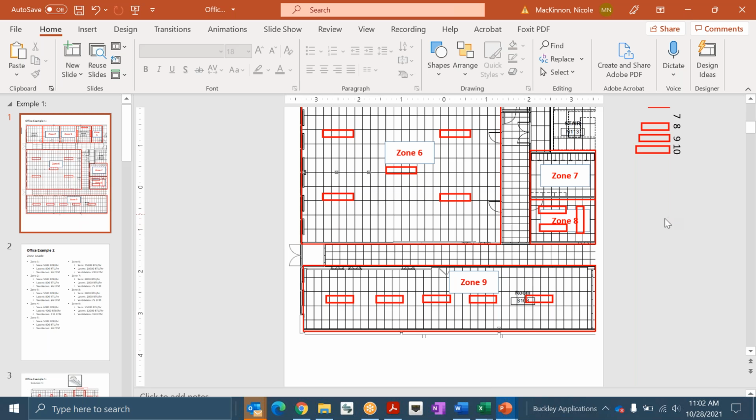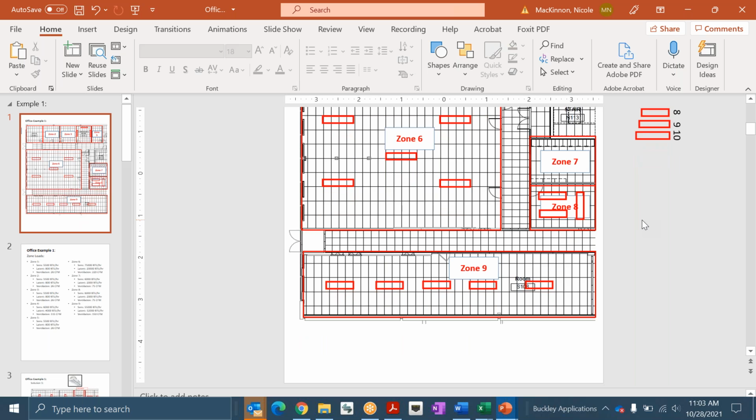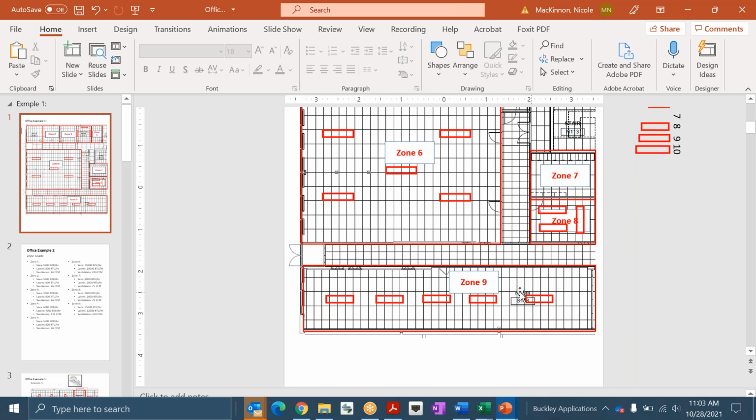Maybe you have a lot of glazing, a lot of solar gain. You don't have a high enough U value on your windows. That could cause some issues. But generally, if you're anywhere from 20 BTUs per square foot up to 50, you're probably okay. I would say 35 is kind of the middle of the road that we see pretty often, and that may even be high for many applications. So in this other case, zone 9, we're nowhere near that level of density. We're comfortably able to fit 5 8-foot chilled beams in here.